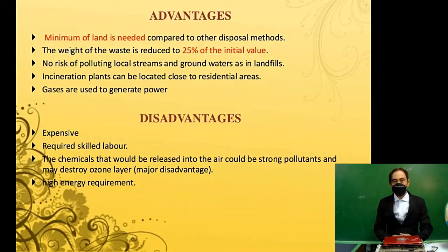So advantages of incineration: minimum of land is needed, of course, compared to other disposal methods. The weight of the waste is reduced to 25% from 100. So this is a waste reducing method. No risk of polluting local streams, grounds, waters as in the landfill. Incineration plants can be located close to residential areas. Gases are used to generate power, but the disadvantage is it is very expensive to have that kind of plant.